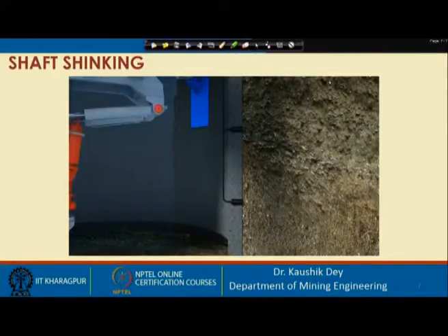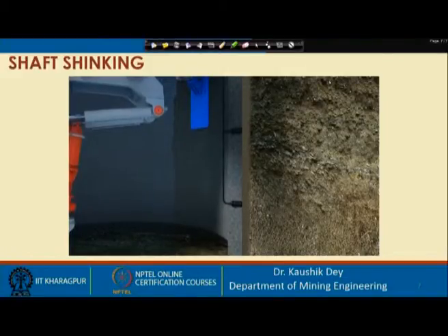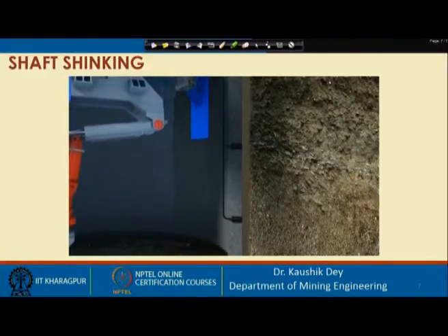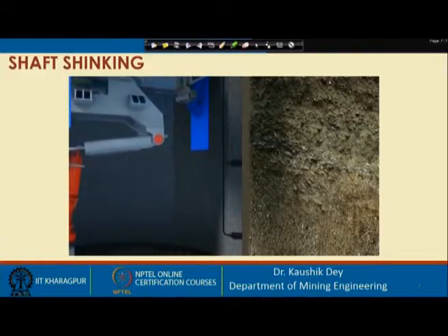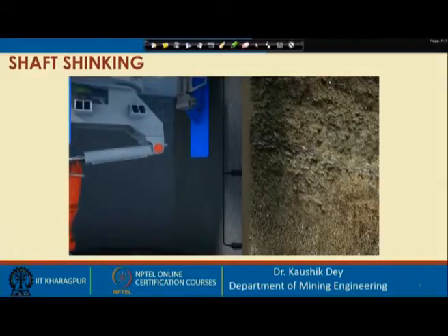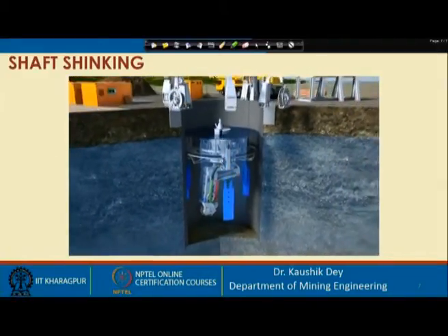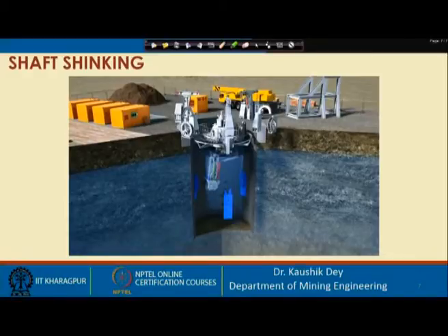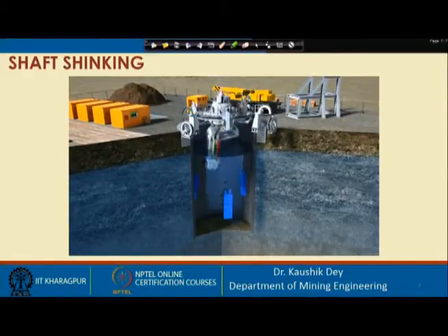An automatic bentonite lubrication system reduces friction between the shaft exterior and the surrounding ground during shaft sinking. To make lowering easy, the total number of nozzles is designed to suit the soil conditions, and the bentonite is generally spread between the casing and the host rock. When the shaft reaches the final depth, the VSM machine is removed and the concrete base block is cast.